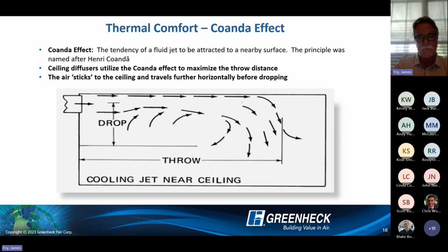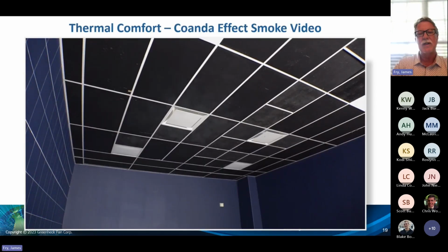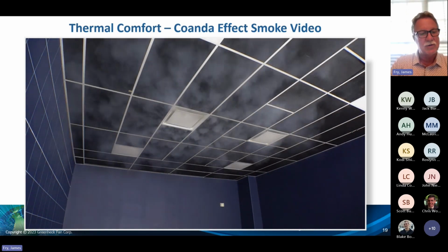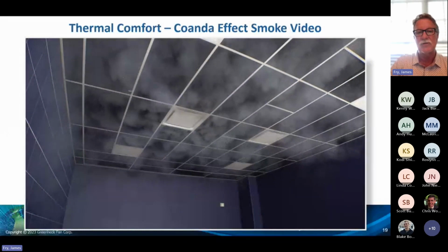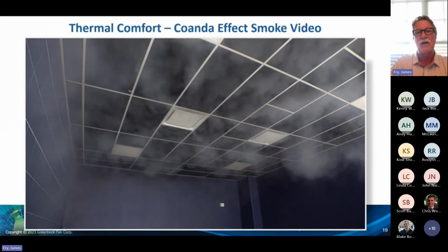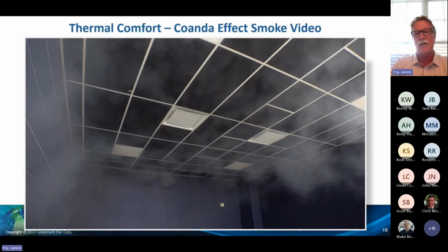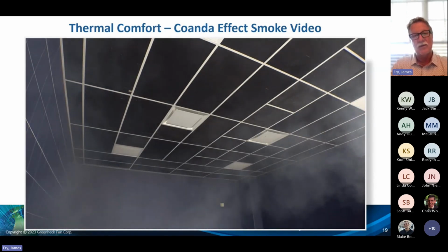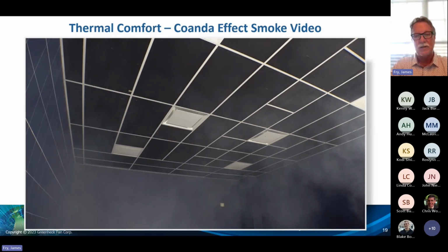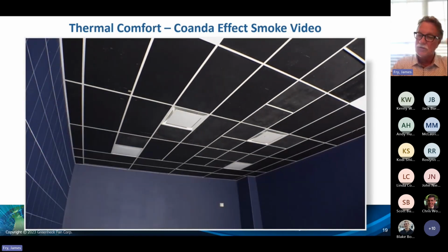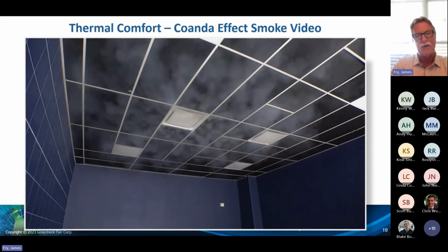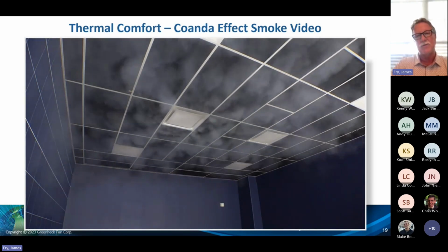30% for your throw. This is our test lab in Clearwater, Florida. This is where we do our standards, demonstrations and testing. This demonstrates the Coanda effect, how the air came out of that plaque diffuser and held onto that wall until it entrained into the room. It will hold onto the surface until about 70 to 100 feet per minute, then start to separate from the ceiling and entrain into the room, into your occupied zone.